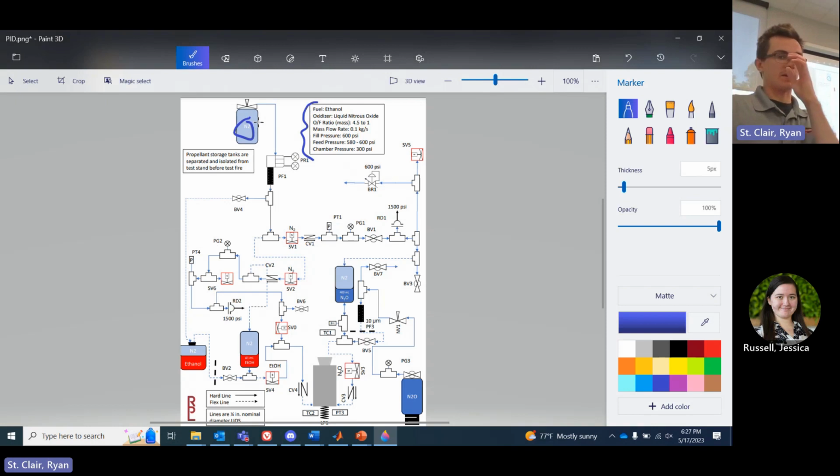That was kind of a segue, but going through the path of pressure right here, nitrogen goes across into this regulator, and it reaches a particulate filter. That's just because our regulators come with particulate filters, so we thought it accurate to include that there. Then it goes across this flex line and reaches this first control valve. This is that solenoid valve I was talking about before. Each of these solenoid valves is labeled. So this is solenoid valve 2. When we want our full system to be pressurized, we open solenoid valve 2. And then all of these lines that are touching here are going to be pressurized to what this regulator is set to.